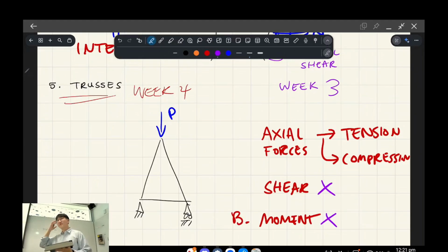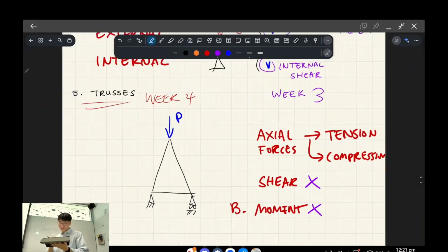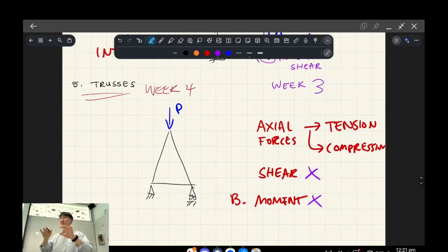So how do you set up your truss? Firstly, one thing I haven't said is that a truss can't be a single member. A beam can be a single member, a straight line. A column can be a single member. A truss can't be, because a truss is a series of members that behave together to achieve the goal of carrying only axial forces. So a simple truss, at minimum, has to be a triangle with 3 members.